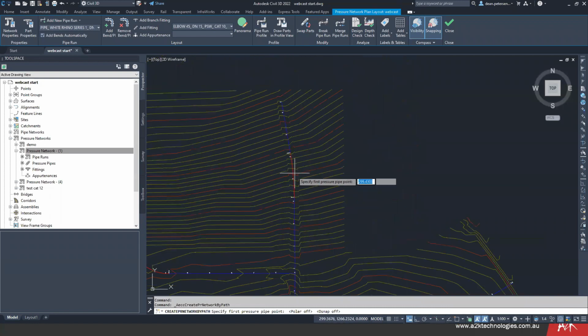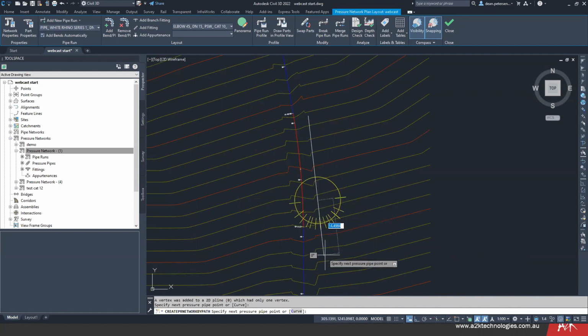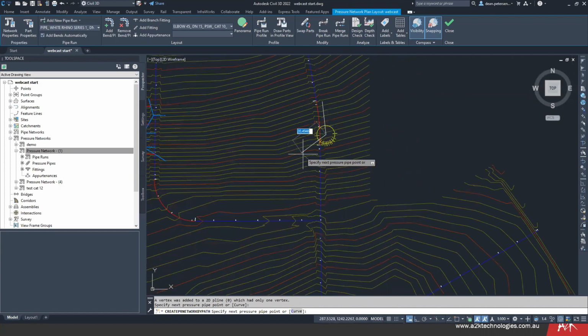You can see in the contours here there's a bit of a road, so I'm going to start laying out the first pipe from here to there. And when you do that, it looks at your catalogue and finds all the bends that could potentially fit onto that 150 pipe. And these are all the angles that are in the catalogue. So it's snapping to those and allowing me to draw for as long as I want it to. So I'm going to put a bend of that size in it, go across the road, and then come to the south.